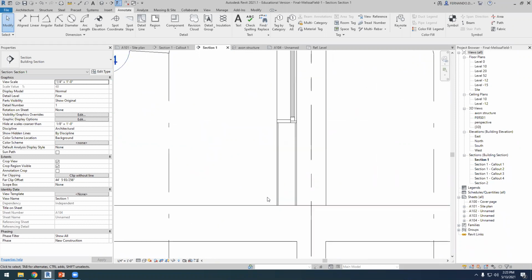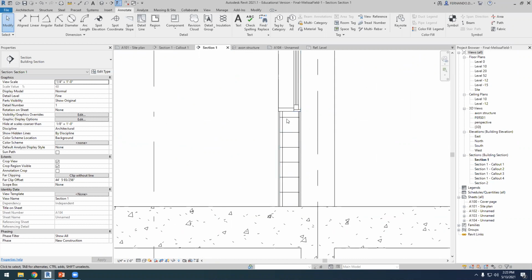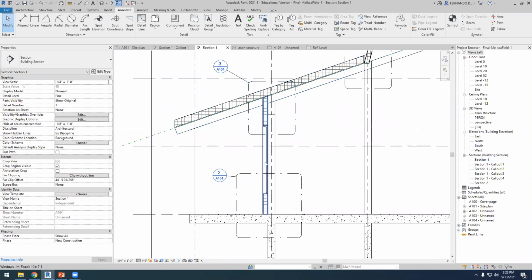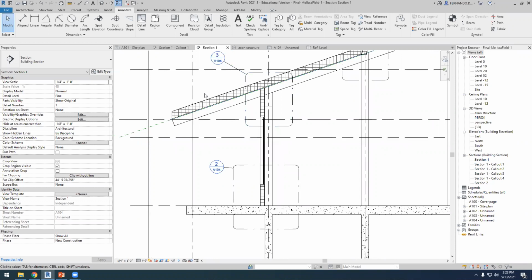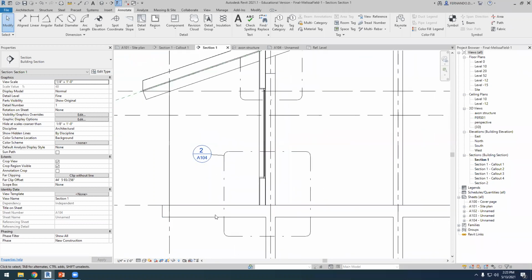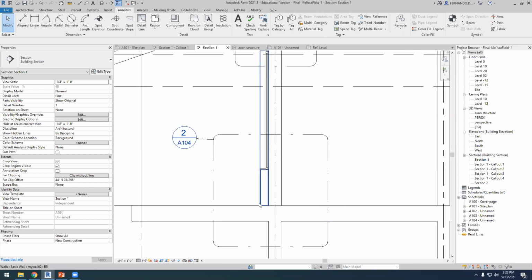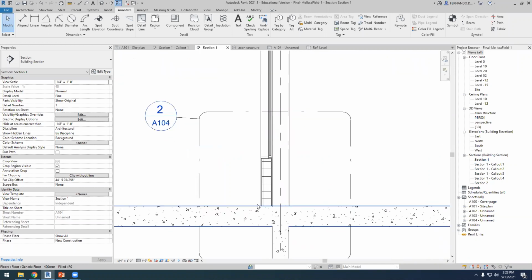And if it stays here, it will end up affecting that wall. Okay, so this is always something. If we didn't have the overhang, it would be even worse. So we have to be even more careful. So here we have the overhang, we protect this, but even if it's protected, there's a risk that the water can stay here, and water cannot stay.